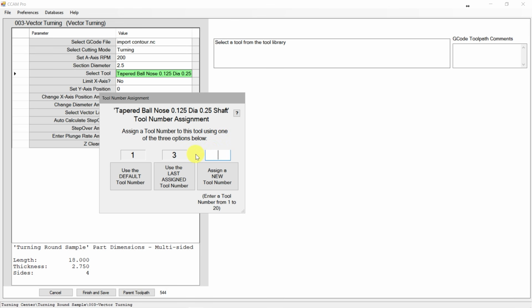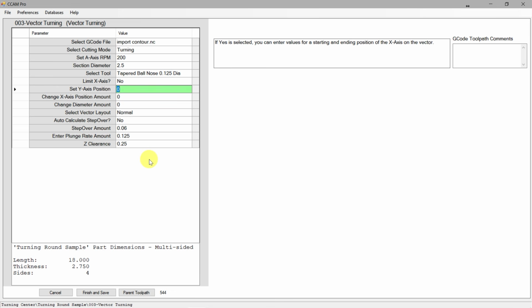Because this is being applied to a spindle that already has existing tool passes tied to it, for example, the surfacing cutter is tool number 1 to turn the stock round, and the classic spiral was tool number 2 to turn the tool profiles, here we're going to make this one tool number 3, just to keep things in linear order of the cutters being applied to this spindle. Now, these are all other things that we can control and do with the platform. We'll cover these in other videos. I just want to get you started with the basics.